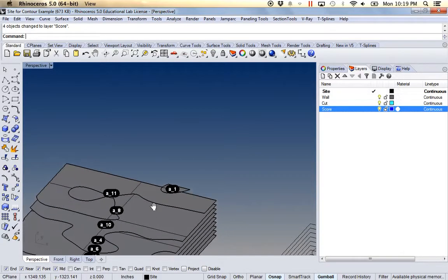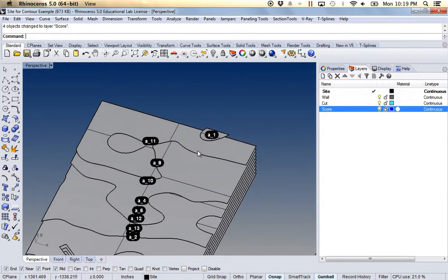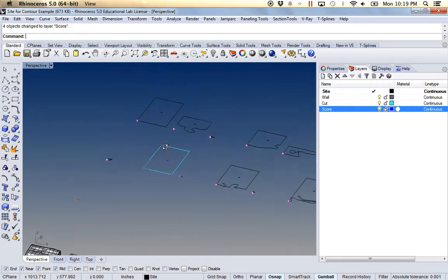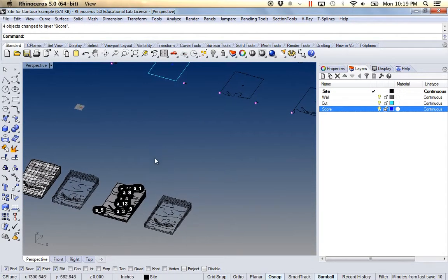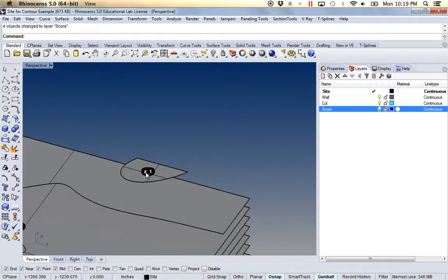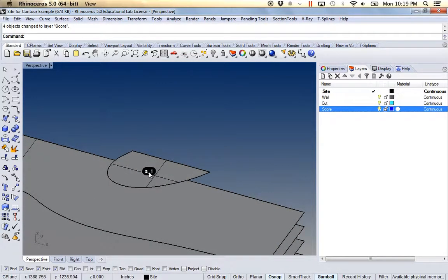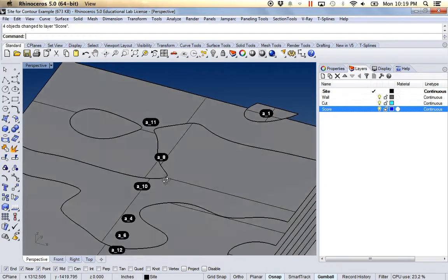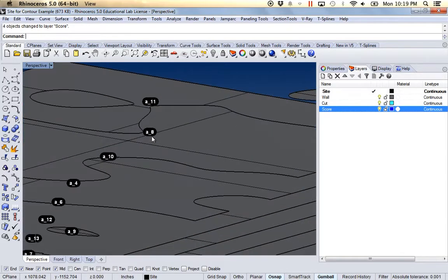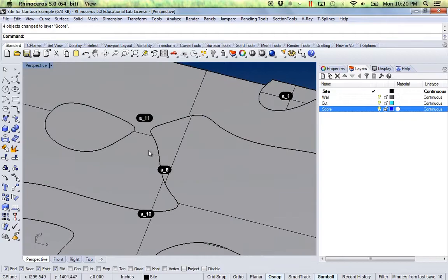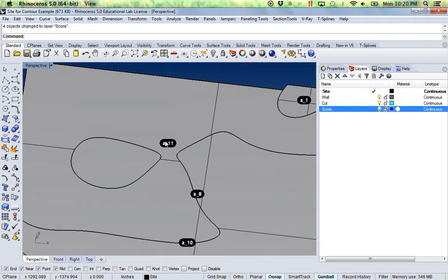When I put my model together, I don't want to see any of the actual scored numbers. Right? It's kind of like a rookie mistake, like when you leave the barcodes on your basswood models. So with the top pieces, for example A1, I don't even want that one to be scored. In my example, A8, I just want to make sure that score is in a location where A11 is going to cover it.